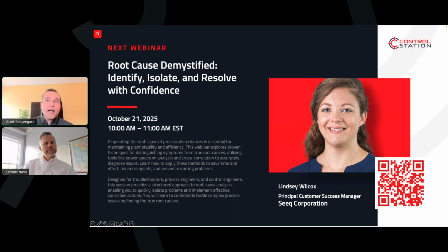An additional consideration you might have there is, how am I going to perform my tests? Because you want to make sure that your tests are indicative of the real process conditions. And so if you have fighting between valves and things like that, those are also going to be considerations that you want to include in the first step, which is, what am I even trying to accomplish here? I would say that the two most difficult parts would be that step, and then sometimes finding a spot, so I would say that yes, defining the control objective and getting the data would be the most time consuming parts of the process, just because there are various things that you want to consider.